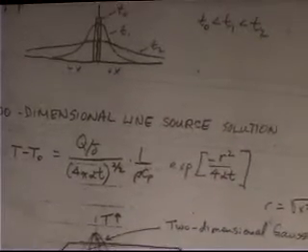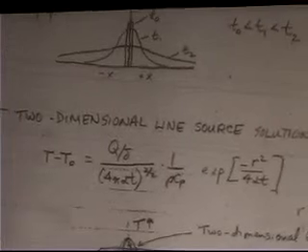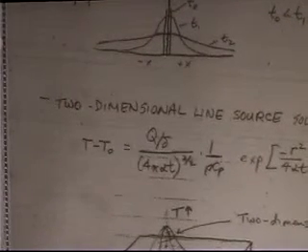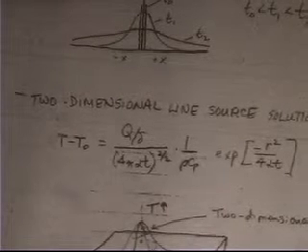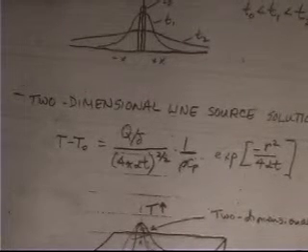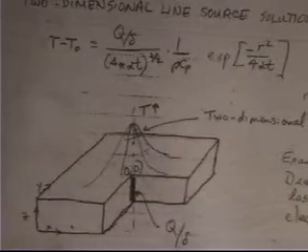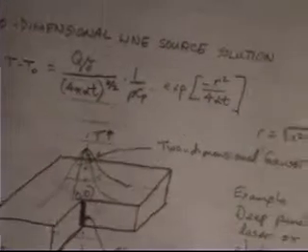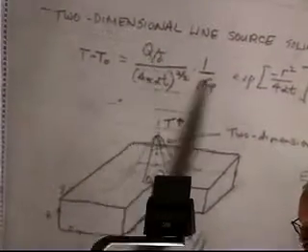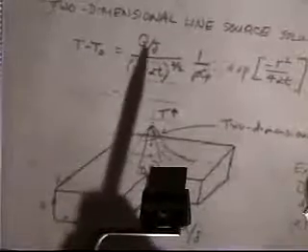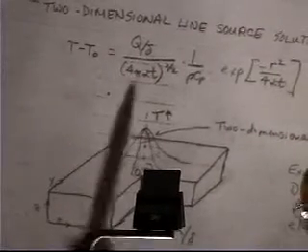if you're familiar with Gaussian being a kind of statistical probability distribution. You can do the same thing in two dimensions where you have a linear heat source, and this is not all that different than something like a laser or electron beam weld where you have a very deep penetrating line source. And now your Gaussian is a two-dimensional Gaussian radiating away in two dimensions from that linear heat source. Okay? It turns out here I had a 1/2 power for this. Here it's a 2/2 power. And here I have a Q over delta. Instead of Q over area, I have Q over, this is heat per unit length of the line heat source. This is the intensity of the heat along the line.